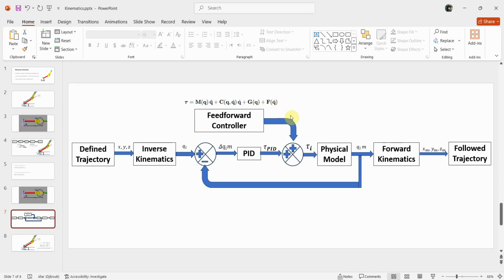In fact, calculating all these terms analytically is very complex because of the geometry and interdependence of parts in the robot. For example, the mass distribution and link shapes make the inertia terms very difficult to derive in our model. Actually, in our model, the only term we compute manually is the gravity torque, which already provides a significant improvement when added to the control algorithm. As we will see, this simplified feedforward term improves trajectory tracking remarkably.